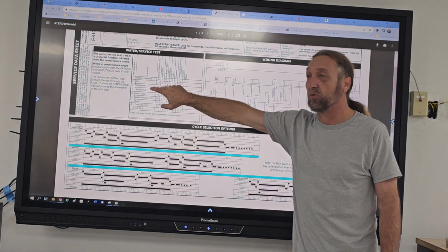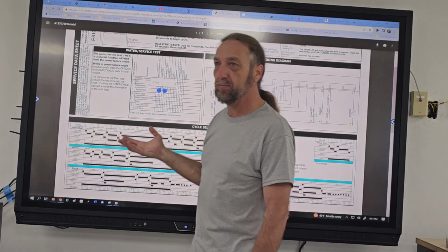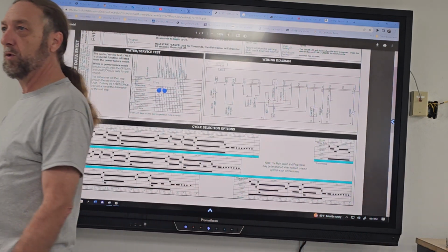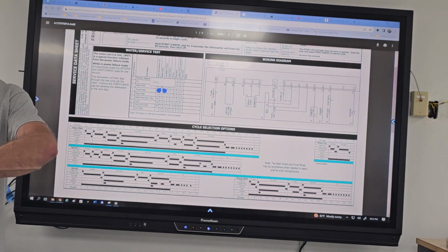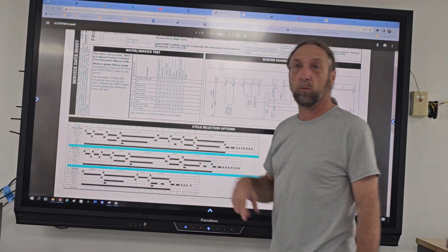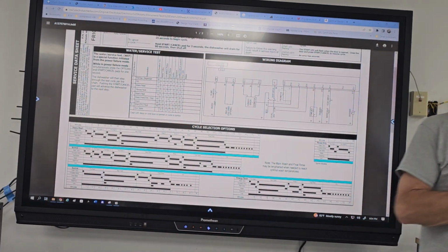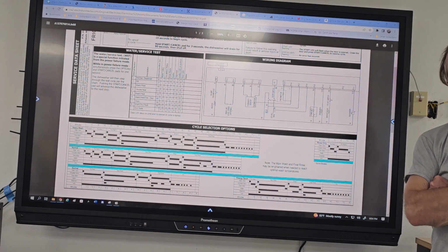I'm in the middle of this wash heat cycle. What do we do now if we don't have power at that point? We know now, by my watch, I'm already 2 minutes into the cycle. 2 minutes into the cycle is definitely gonna put me in the middle of that wash heat, right? Do we check power at the board? Or we check the board to see if it's sending power to the heater? How would you test that?